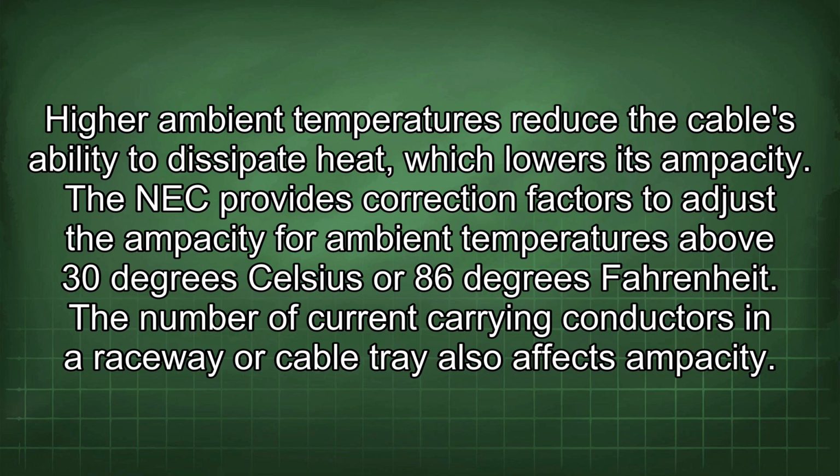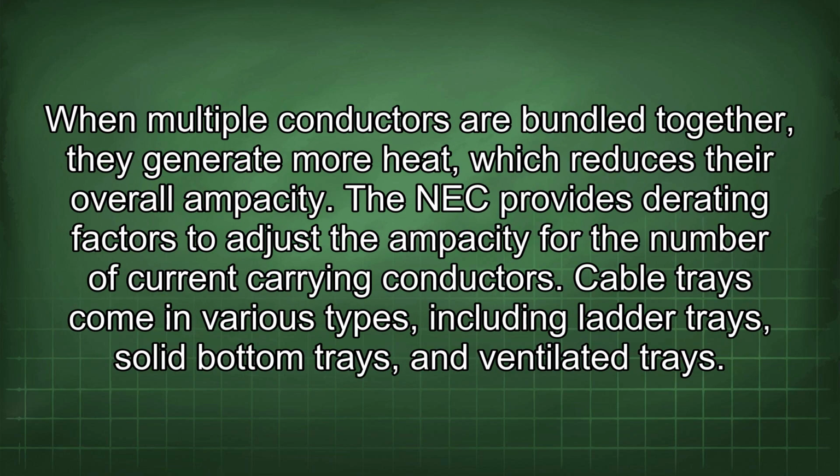The number of current-carrying conductors in a raceway or cable tray also affects ampacity. When multiple conductors are bundled together, they generate more heat, which reduces their overall ampacity. The NEC provides derating factors to adjust the ampacity for the number of current-carrying conductors.